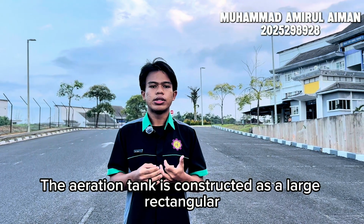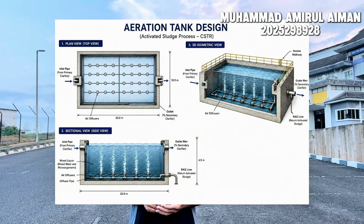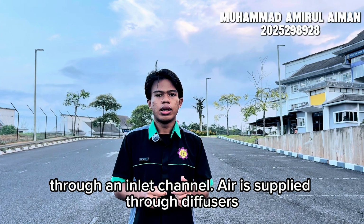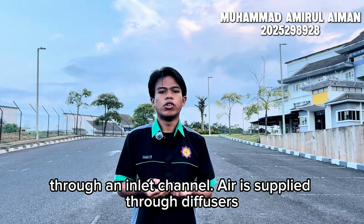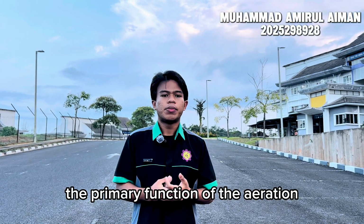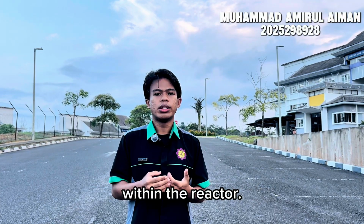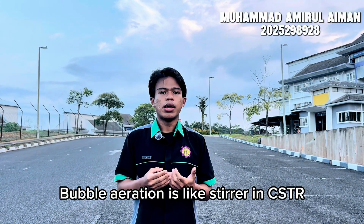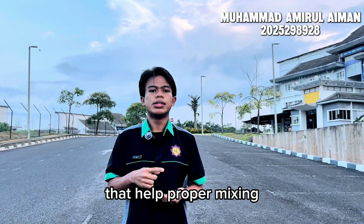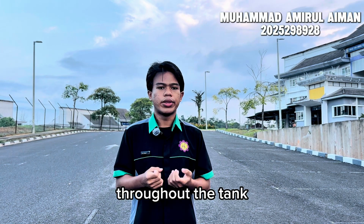The aeration tank is constructed as a large rectangular tank equipped with an aeration device. Wastewater will enter the reactor through an inlet channel. Air is supplied from a diffuser located at the bottom of the tank. The primary function of the aeration system is to maintain mixing within the reactor. Bubble aeration is like a stirrer in CHE244 that helps proper mixing and ensures uniform distribution of microorganisms throughout the tank.